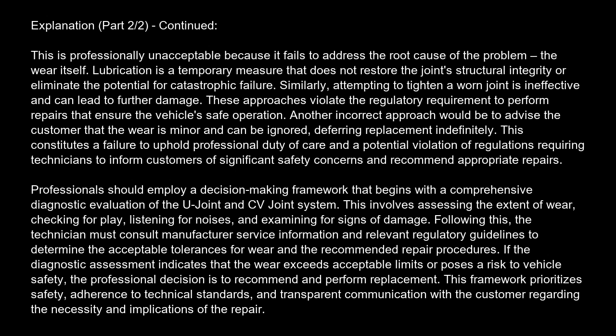Professionals should employ a decision-making framework that begins with a comprehensive diagnostic evaluation of the U-joint and CV joint system. This involves assessing the extent of wear, checking for play, listening for noises, and examining for signs of damage. Following this, the technician must consult manufacturer service information and relevant regulatory guidelines to determine the acceptable tolerances for wear and the recommended repair procedures.